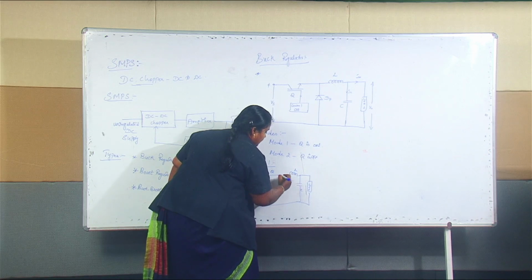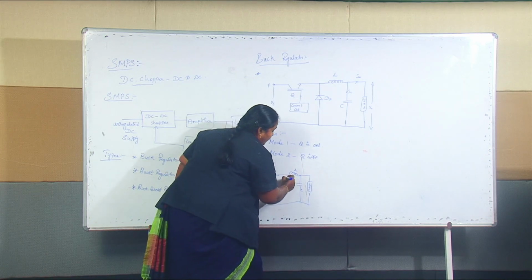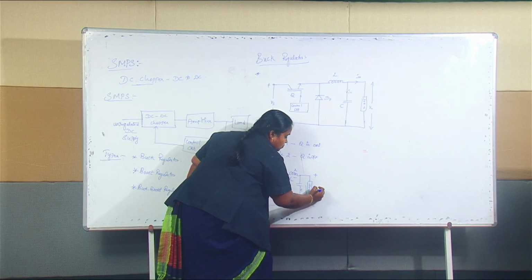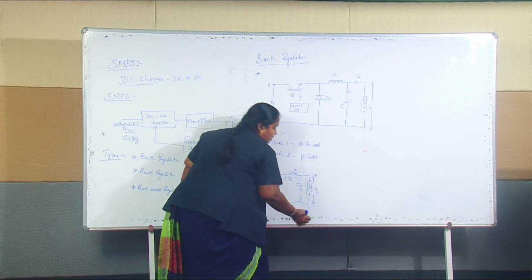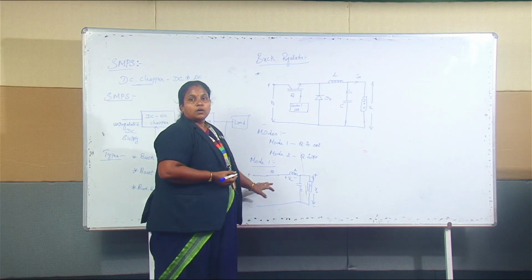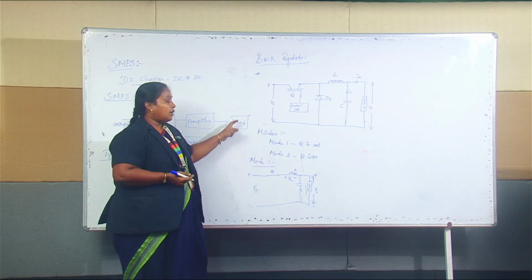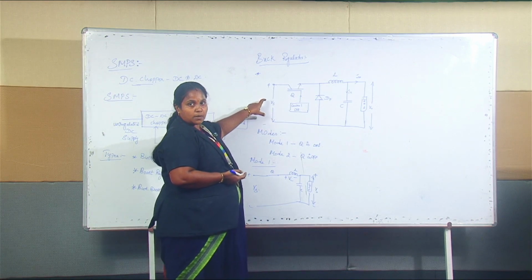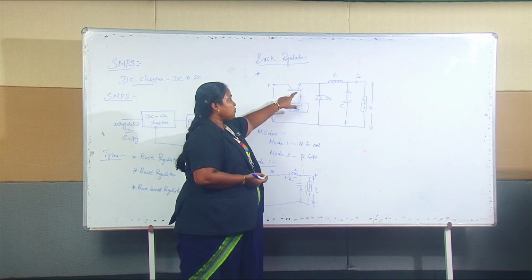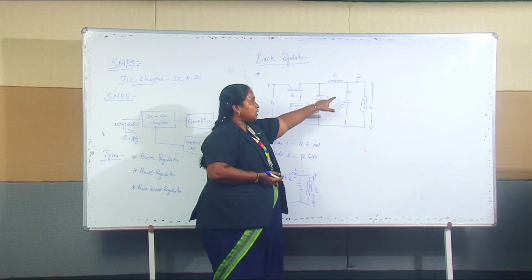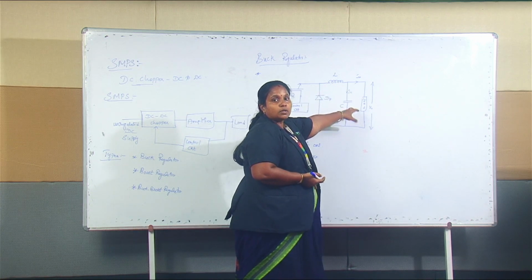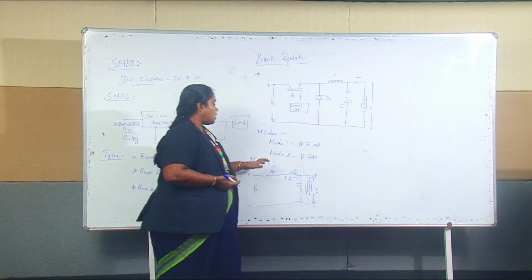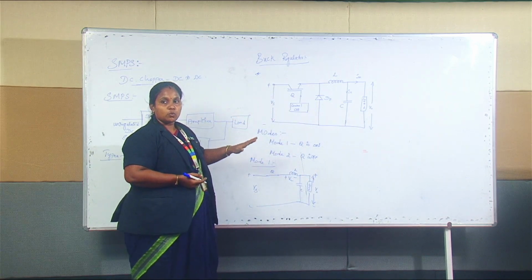Let the voltage across the inductor be VL, with the polarity marked as positive and negative, as we assume this polarity to be the voltage across a load. So this is your circuit. When the switch is turned on, the current from the supply flows into the switch. From the switch, your inductor is getting charged. From the inductor, it flows into a load, which has a regulated DC voltage with the help of a capacitor. This is how your transistor will be operating in the mode 1 operation.